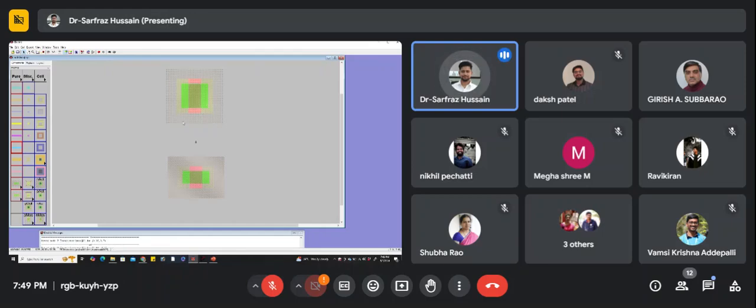Now again, see this one, we have not connected any contact here for the drain and source, so we need to put some contacts here. How do we put the contacts? Here you can see there is N well, there is P well, and there are P active and N active. Active we'll connect later on. At present we need this P well and N well. P well we can put somewhere here, and N well somewhere here, right?